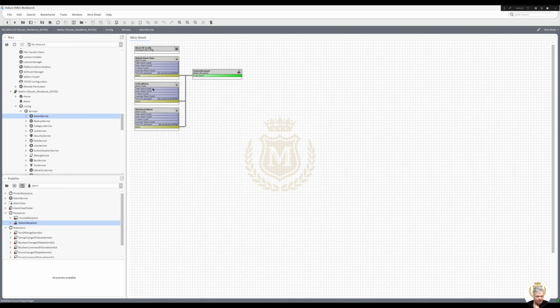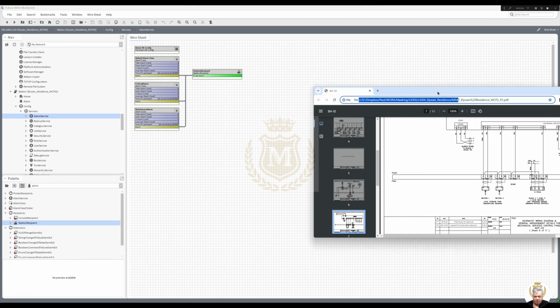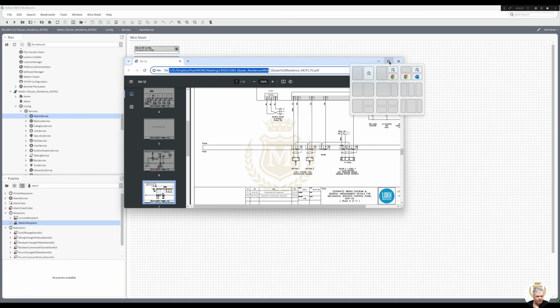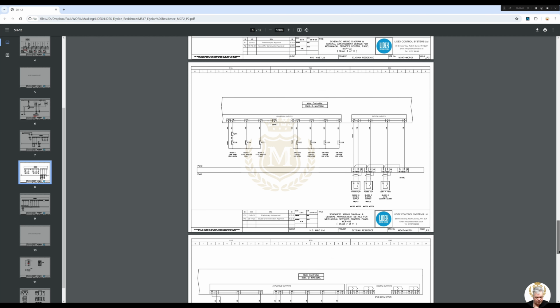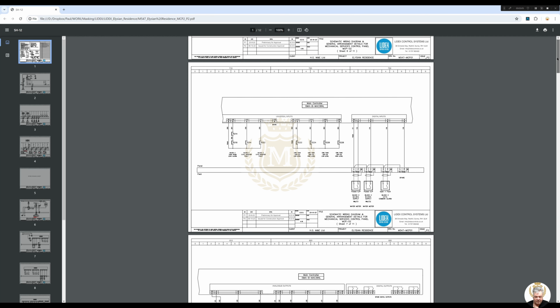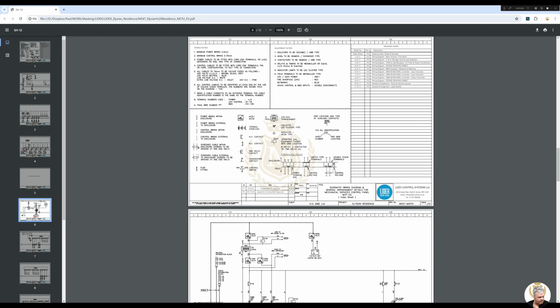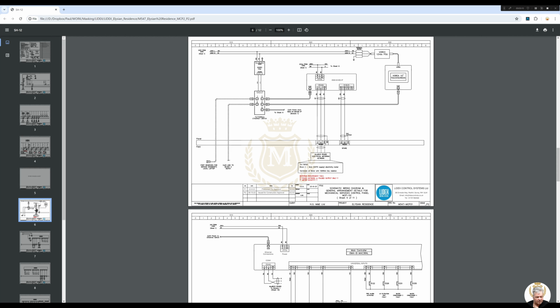Now there is a touchscreen on this station. I'll bring you the drawings across. But what I'm going to do with that is just point it to MCP1's IP address for the touchscreen. Where are we? Touchscreen is there, that one, page 6. So there's your touchscreen. So I'm going to just point that to the IP address of MCP1. So they can log in still with user, etc. They still see all the graphics. But it's not going to be a touchscreen just for this Mac 36 controller.